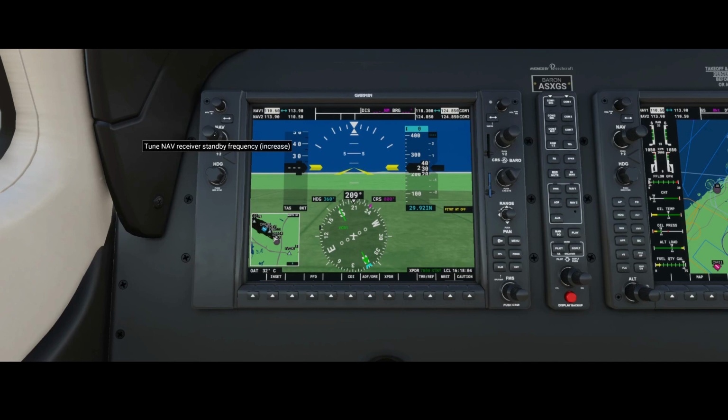So I made a note of it. It was 111.75. So you can use the front knob to change the numbers behind the dot, and then use the large knob to make the change before the dot. Once that's done, press the button again, and you can see that it has activated the waypoint, because you can see the name here, which we already found on the map. Using this option and setting the CDI to 401 before, I would say as soon as we're pretty close to the airport, we'll make sure that we can use the ILS approach using the autopilot.